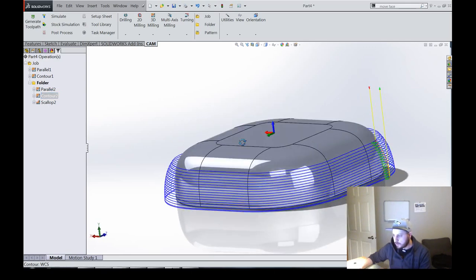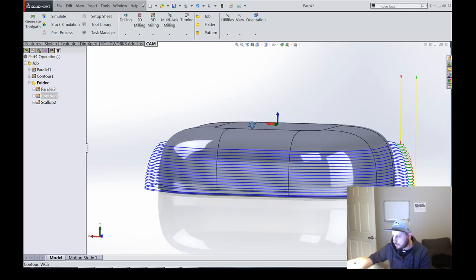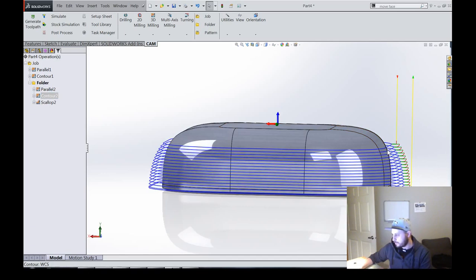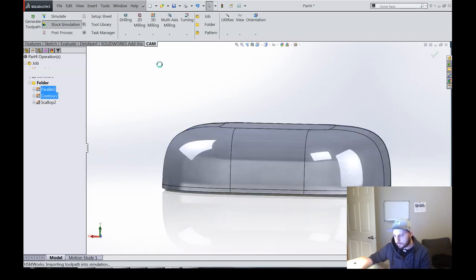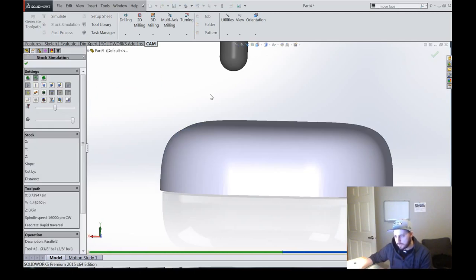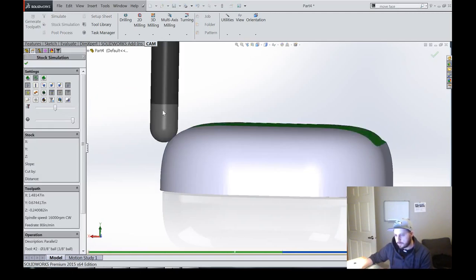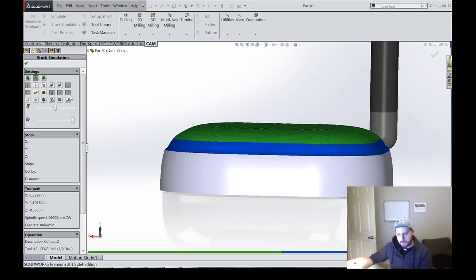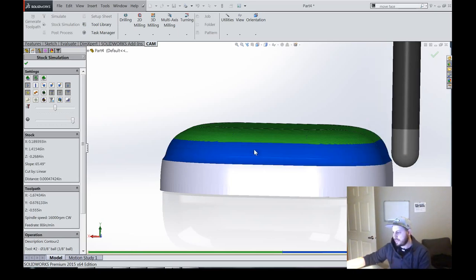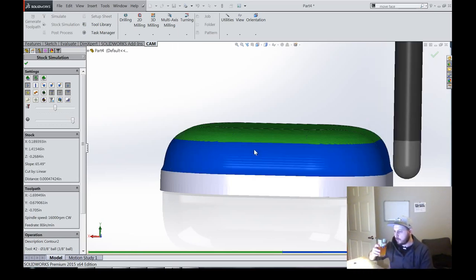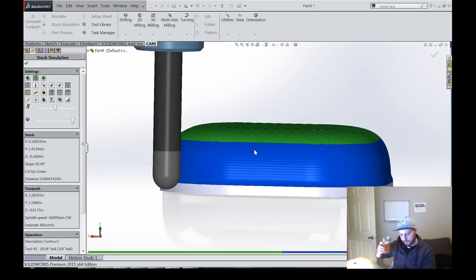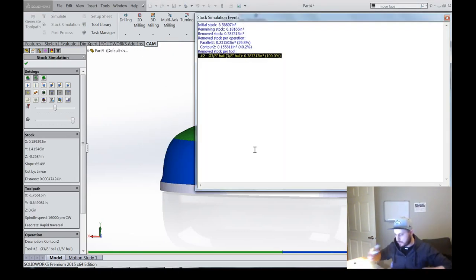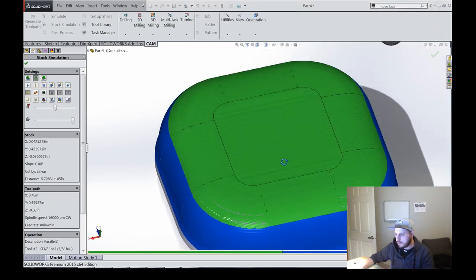And then you do the exact opposite onto a contour toolpath. You tell it to only handle the sections from 45 degrees down to 90. And what you get really is, and we'll see how well this generates here, is really a pretty good toolpath. It just really doesn't do any of this other stuff. It's not attractive in much of any way.